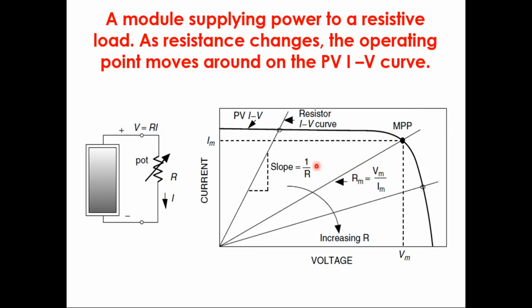This is how the resistance operates on the IV curve. You will find n number of lines over here. If my R is less, or bypassed, I will start from ISC. If I incorporate the entire resistance, I will stop at VOC. In that case, we will have n number of operating points for different values of resistance.